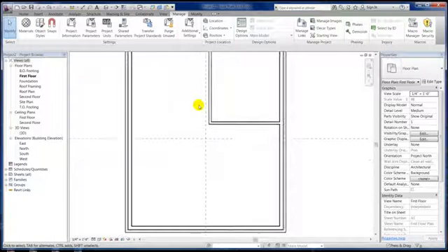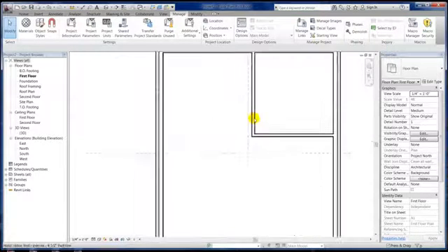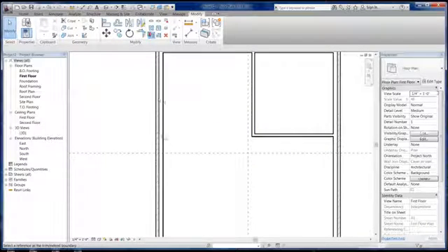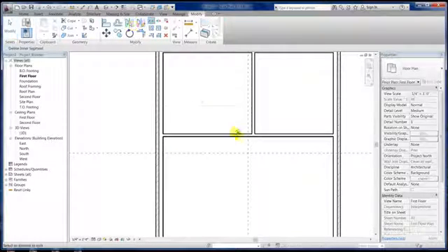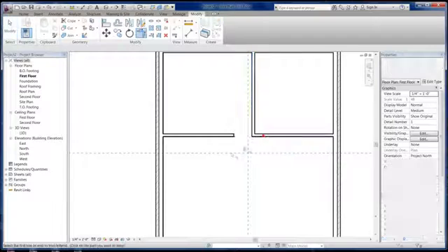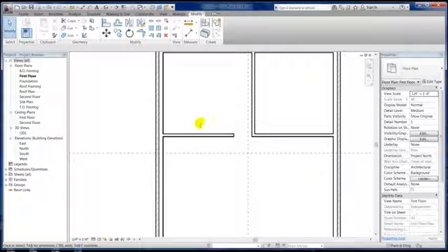So let's go ahead and continue this room over here. There's a couple ways we can do this. I can come in here and extend it to this wall, that wall. So now it's extended, and then I can come in here and split this wall right there. So now it's 2 separate walls. And then go back to my trim command, and that leaves my other wall there. I can also,